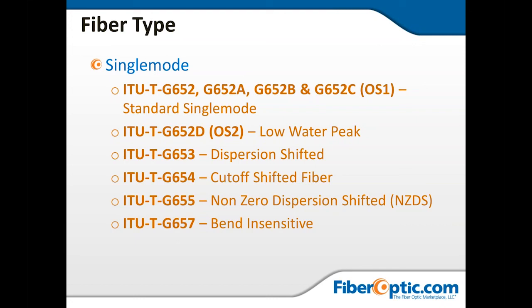They've got some that's designed for outside plant, but the most common type of usage I see with the bend-insensitive is in patch panels, because slack management in patch cords is one of the worst things I've seen for bend radius or maintaining good slack management. And the bend-insensitive patch cords provide us with a little bit of protection in regards to macro bends in patch cords and in head end locations.